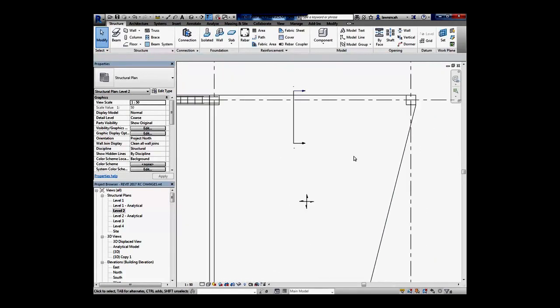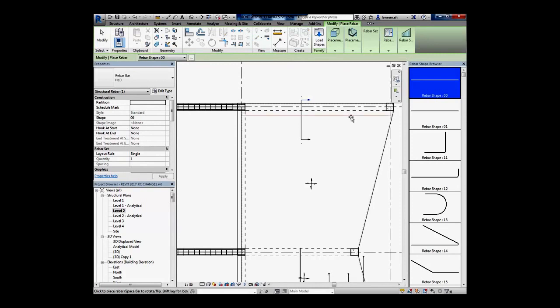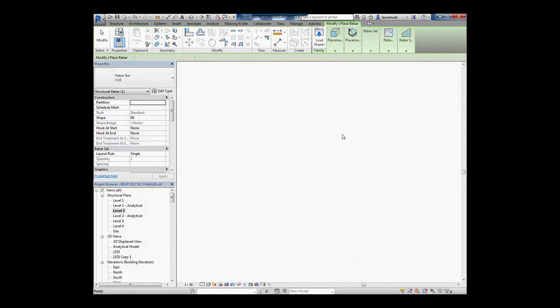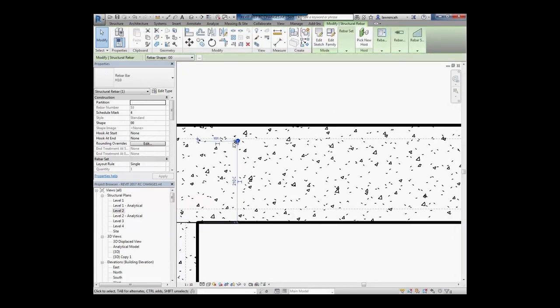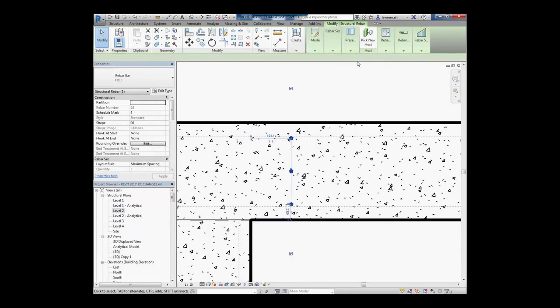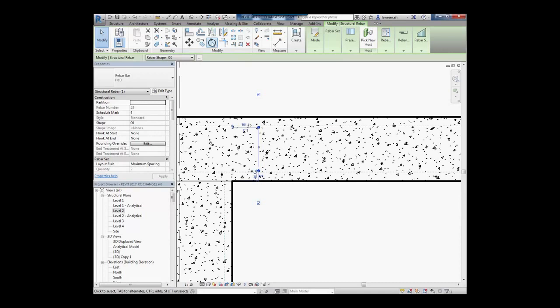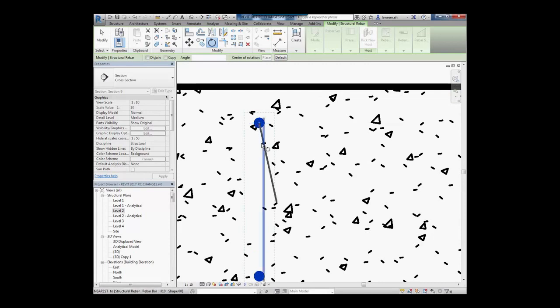Okay, so here you can see that we have a slab in place. What I'm going to do is start by actually adding a reinforcement bar. So in here, we'll go for H10, and we'll place our first bar here. In a sectional view, you'll see that the reinforcement bar has, of course, snapped to cover. We'll now create a range, and perhaps we'll have 300 millimeters between the rebars. And I'm going to rotate that range as well, so it actually ranges across the slab rather than down through the depth of the slab.